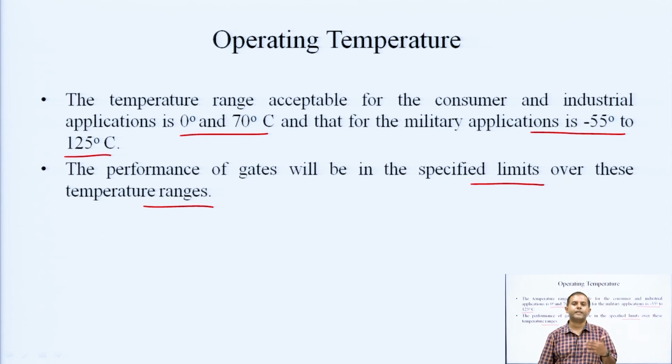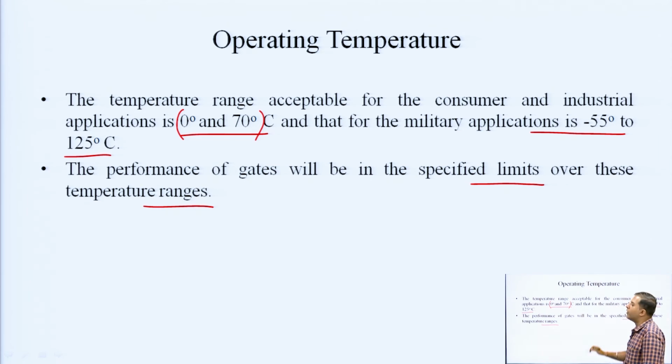If the temperature goes beyond this limit, then overheating can be caused, and due to that the logic gates can be damaged. So, we always try to maintain this temperature band from 0 to 70 degree for industrial and consumer applications, and for military application it is between minus 55 degree to 125 degree centigrade.